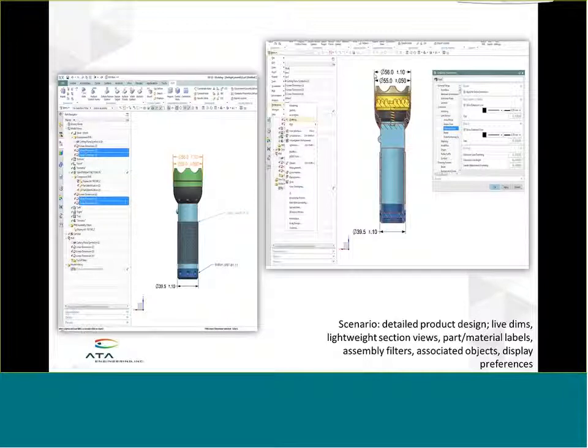And speaking of customization, the preferences for each of these PMI elements is defined using drafting preferences. So just like you can set up part templates ahead of time in your organization so that all of your drafting elements have a unified look and feel that meets your organization's policies and other templates that you have, you can also set up templates for parts that have the drafting preferences predefined so that all your PMI notes will follow the standards that you use within your organization.